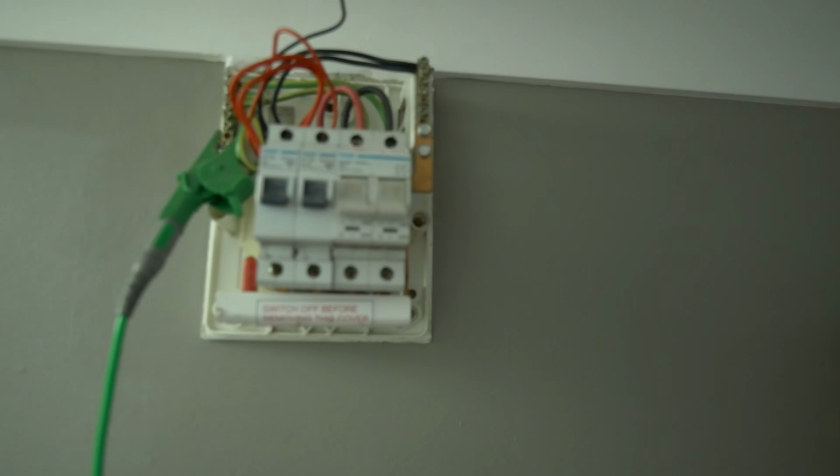Now, we could approach this as a global IR value and see exactly what we get. And if it reaches above 2 megohms, then we're all good in theory. However, this has been a smaller installation. I thought it'd be interesting just to break it down. So I'm going to separate this out. We'll do it at 250 volts first. I always recommend you start there.